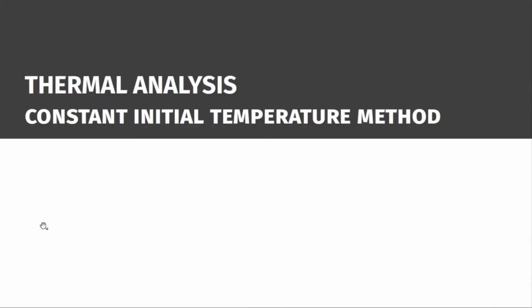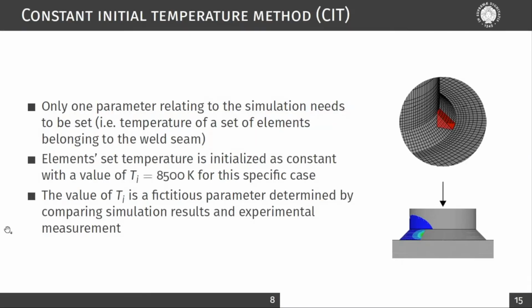The thermal analysis is explained firstly. To simulate the thermal load deriving from the welding process, a constant initial temperature method was implemented. The thermal process was initialized, activating a volume of elements at a starting temperature Ti, where Ti is the only parameter this method needs to work properly.